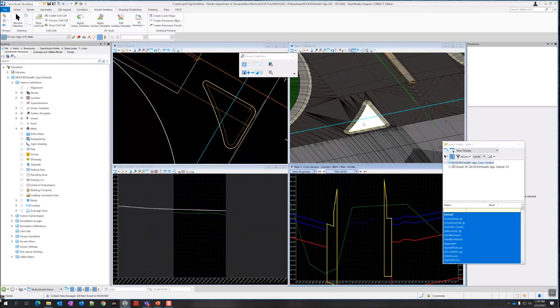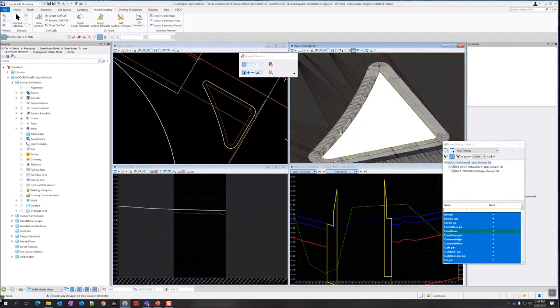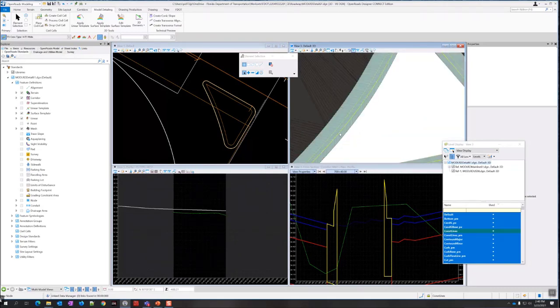So the only thing we need now is either sod or concrete in here. I think for the exercise, it's supposed to be the DTM proposed slope. So for sod, and if you needed concrete, you can just create a terrain the same way and add a surface template on it. First of all, we need to create template geometry for this curb back. So if I hover over it, make sure I get the right one.